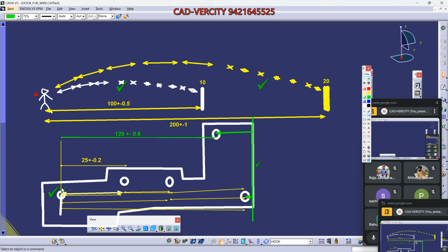With the help of that principle, what is a datum? With the help of the 3-2-1 principle, we will finalize, okay, this will be my datum. This face will be my datum. And again, I will need one datum along Z. So let's say this face will be my datum. So what I'm doing is locking this motion. Also with the help of the hole, I lock the up and down and left to right motion. With the help of the axis also, I have closed the motion.